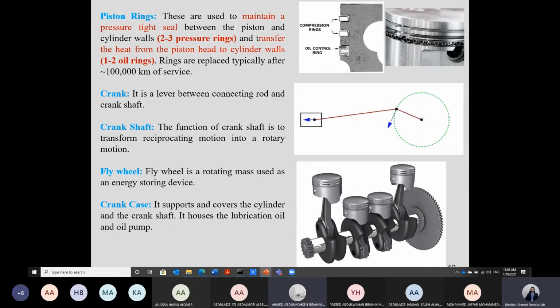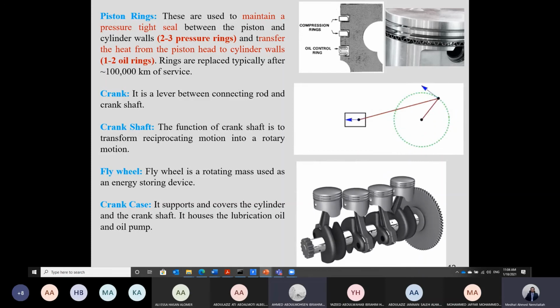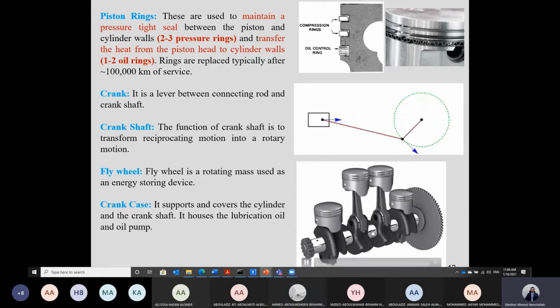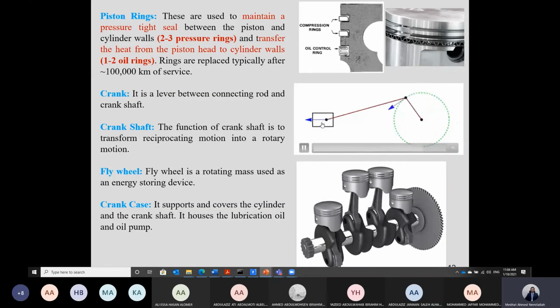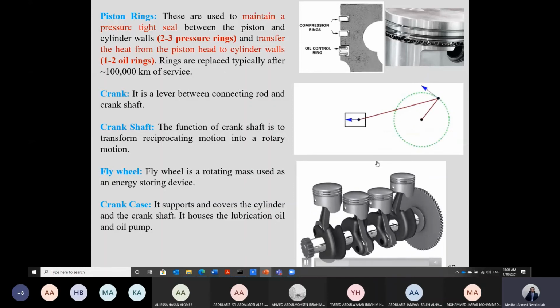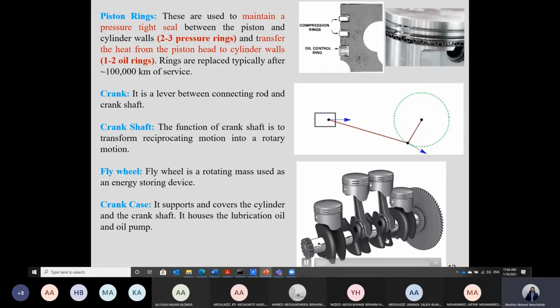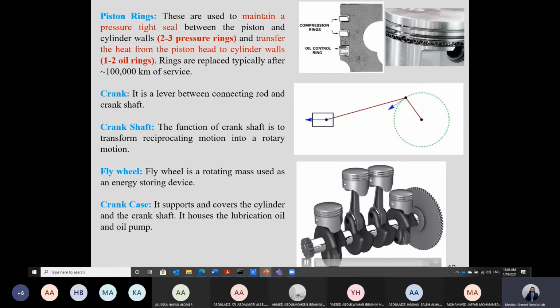To reduce the vibration. Yeah, exactly. The function of the counterbalancing weight here actually is to reduce the vibration. As I told you, the motion of the piston is reciprocating, so it results in vibration. So we have to generate a stable rotating shaft here. So we have to have counterbalancing weight in this case, connected to the connecting rod.